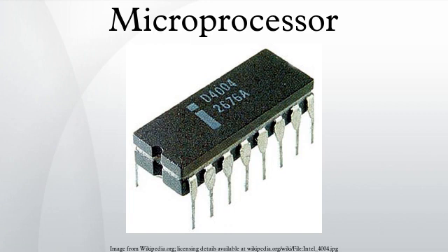A follow-on chip, the TMS 9980, was designed to compete with the Intel 8080, had the full TI 990 16-bit instruction set, used a plastic 40-pin package, moved data 8 bits at a time, but could only address 16 KB. A third chip, the TMS 9995, was a new design. The family later expanded to include the 99105 and 99110.